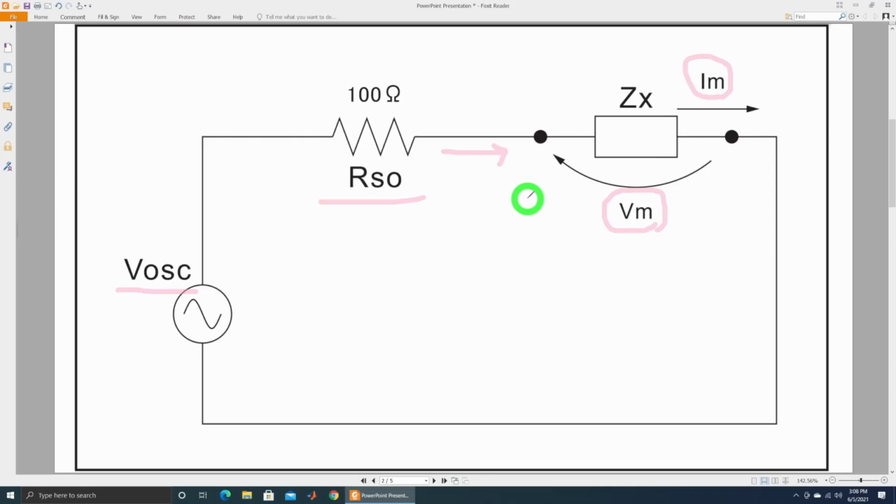But it's not so simple as that, because as you move the cable around, you're going to create a whole new environment. These cables couple to the environment in different ways. For example, they can capacitively couple to the environment around you. And this capacitance is going to mix with the device you're measuring, and as you move the cables around and things become close to it, you're going to have a different capacitance each time. And of course, you can also create a magnetic field because you're applying an AC signal through a conductor that's going to create a magnetic field. And that's going to couple to other lines into mutual inductance, and then that's going to add up to your measurements too.